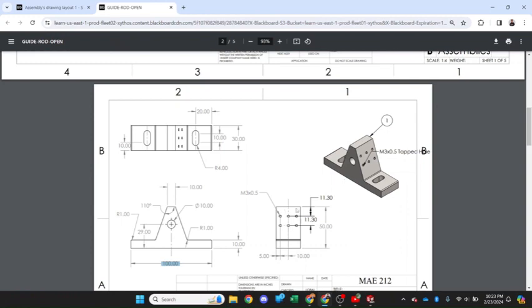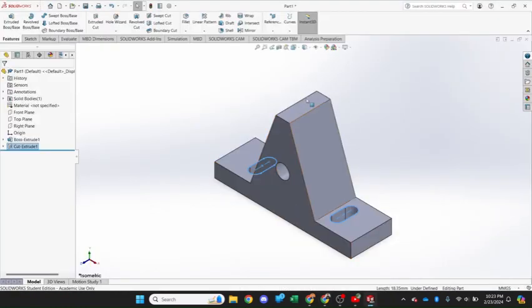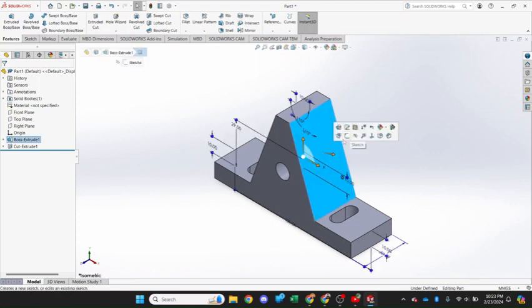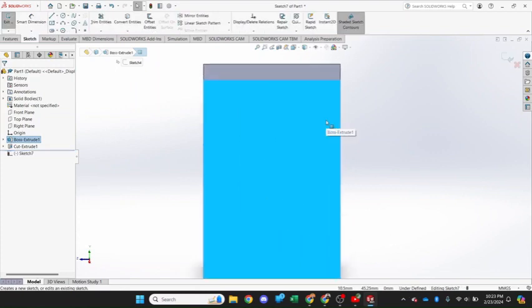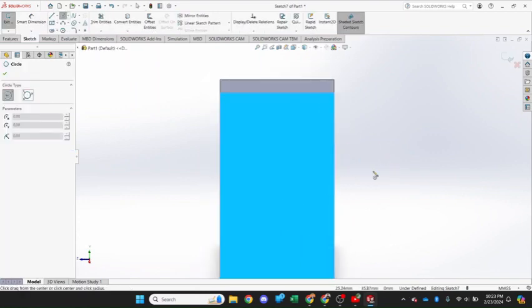Then we've got to do these. So this is not actually a hole, it's a special M3 by 0.5. I'll get to how we do that. So we're going to come onto here, single click, sketch on this side plane here. All we need is a single circle.